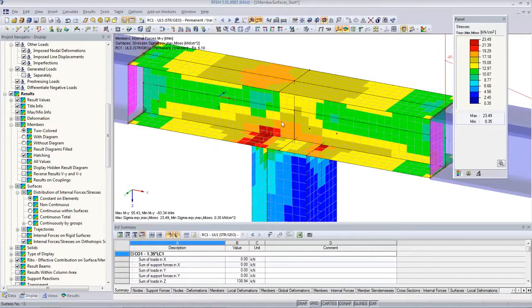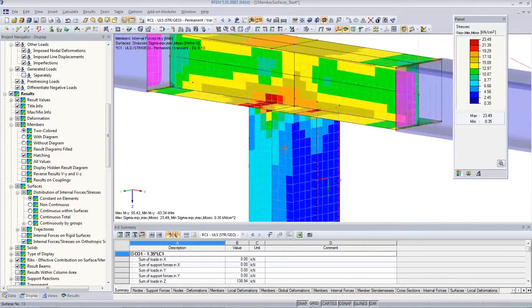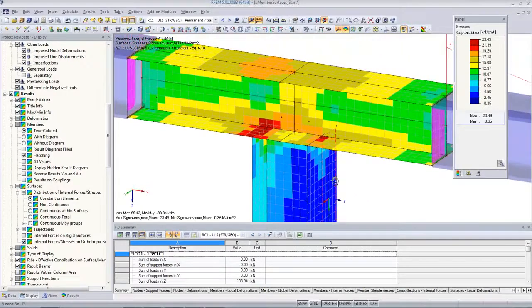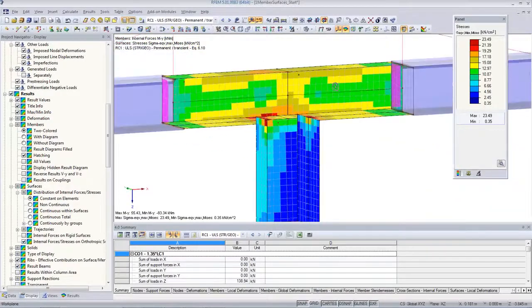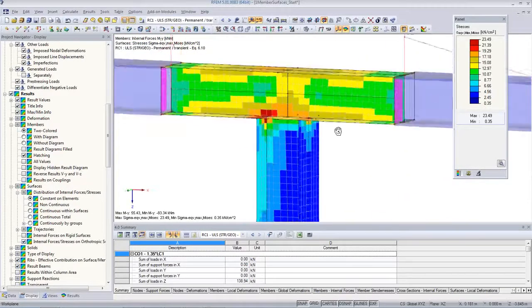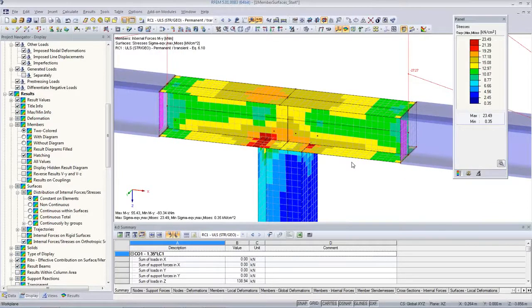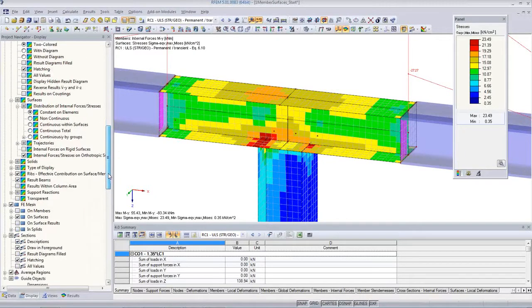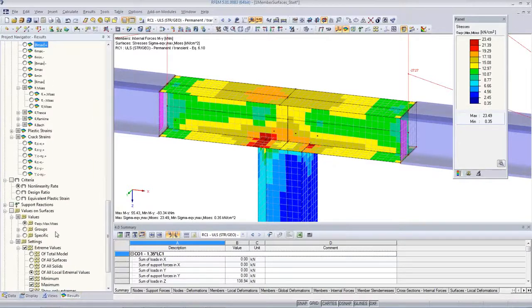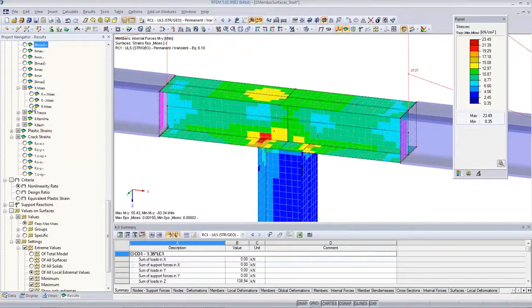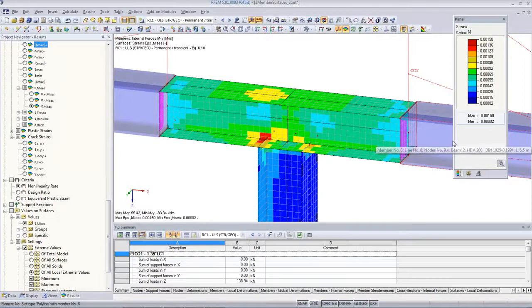We see here the red areas where we actually have the stress. It's a slightly bigger area than we saw beforehand, where we thought there was an extra overstress. This is due to the redistribution of the forces, because we now also have a different stiffness through the plastification. Also, I can take a look at not only the stresses, but also the strains, because I have to make sure that I do not have endless strain in the material.